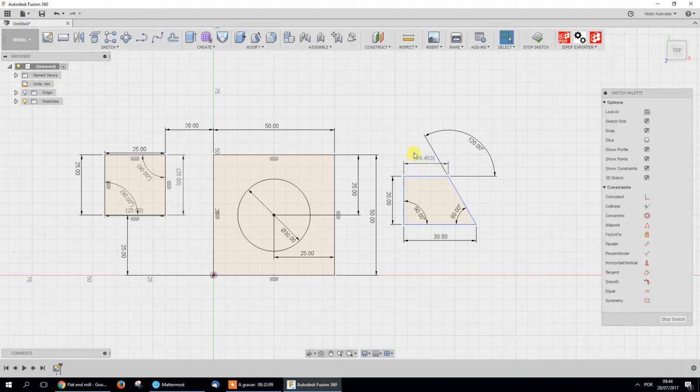What I was saying is, if this is driven, it's between brackets, you can maybe remove one of the measurements and just right click, toggle driving. And in this case, now I can change to 30 if it can solve. In this case, it can't solve because of the constraints I placed.